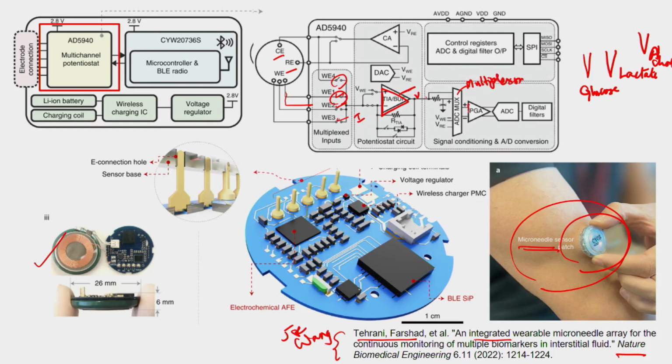But anyway, this voltage is again amplified. Amplified means the value is increased. PGA stands for programmable gain amplifier. Let's say I have a signal which is 10 microvolts and I want to amplify it to 100 microvolts. Then I will multiply it by 10, so the gain is 10. If I want to multiply it by 1000, then 10 microvolts becomes 10 millivolts. So I can choose how much gain, or multiplying factor, I want on the signal.